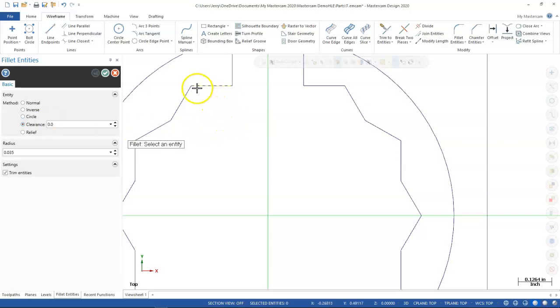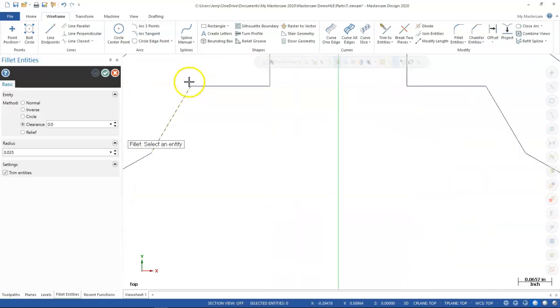Usually, if that was my sharp, and I was to draw a circle, I want just a partial, and let's just say, I will take a guess. The maximum allowable value equals 95% of the fillet radius. Distance is measured along the fillet radius from the intersection of the entities. When I've traditionally done this, it's been about 10 thousandths. So we'll start there and we'll go up.